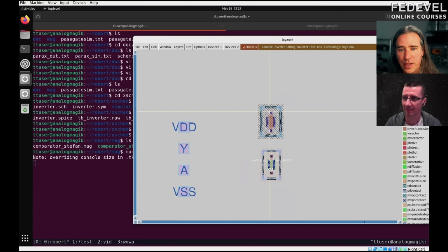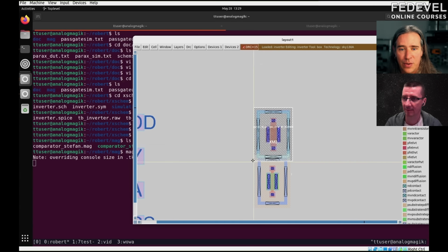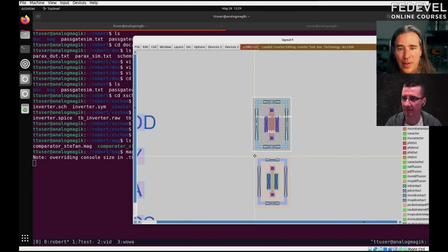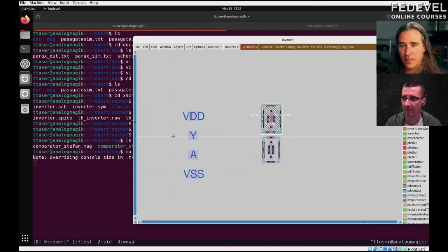So all you have to do is find a placement where you're happy. Now, that's, for me, a bit of trial and error, because if you get too close, you start getting DRCs everywhere. So I just want it as close as possible before I get extra DRCs. So I'm at 12. That's good. So what do we have? We've got VDD, this guy. And, by tradition and just because I like it on top. VSS, this guy. Put him on the bottom. Well, bottom-ish.